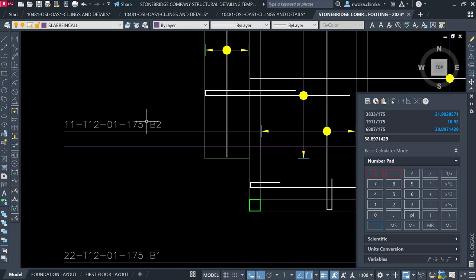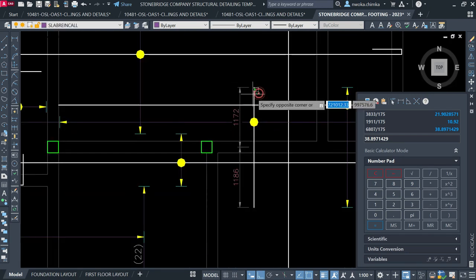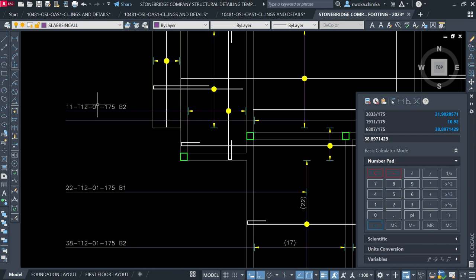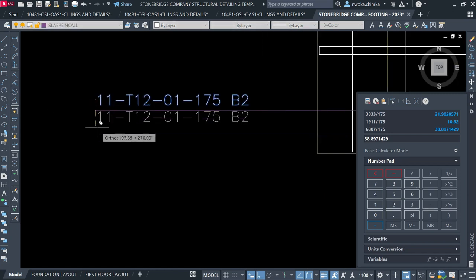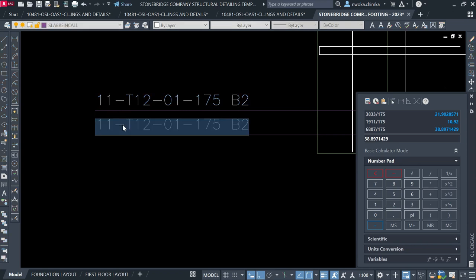So I'll go here right now and copy this just now, and this is now a top. Now don't forget, this is a top reinforcement. This one here is a top reinforcement along this continuous beam. Okay, so right now go here, copy this and place this here, and then come here right now and put the value there, which is 39.